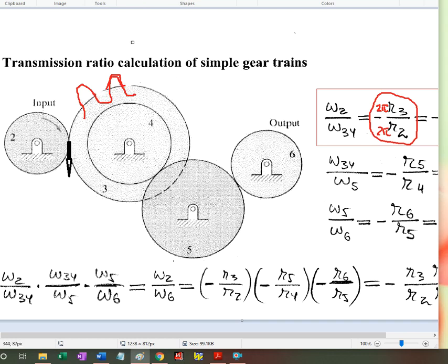And we define the circular pitch as the length of the arc between, and I overshot, so this is the circular pitch. I need to erase again. So the circular pitch, lowercase p, is going to be the length of the arc between one point and the corresponding point on the next gear. So if I divide the circumference by the circular pitch, it gets me the number of teeth.